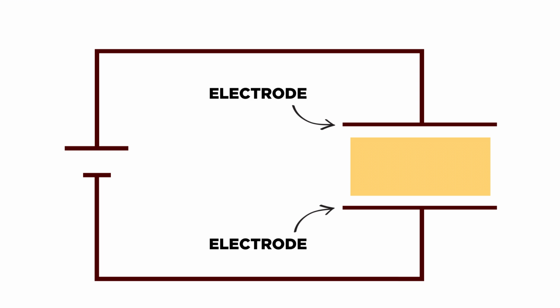Now, imagine two pieces of metal instead of a balloon and a cloth. Put something in between that prevents them from touching each other, and finally replace the work you put in with a voltage source. You now have a capacitor. Basically, a capacitor consists of two parallel metal plates, called electrodes. They are physically separated from each other by an additional layer, called the dielectric, that can be made of specific materials, like plastic or simply air. This means that the plates are not directly connected and, as a consequence, there is no current flow between them.